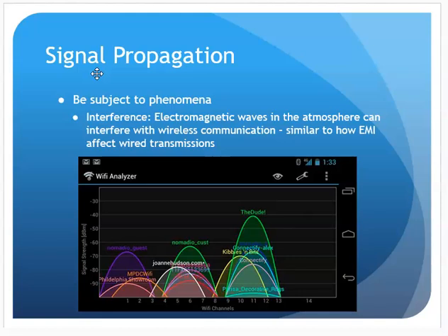There are plenty of things that are broadcasting in our wireless bands now. And I grabbed this sample offline, but this would be, if you use a Wi-Fi analyzer wherever you live, if you live in a neighborhood, you're going to end up seeing this. You're going to see a ton of SSIDs on different channels in your frequency band. These could be all of your neighbors. Well, if I'm trying to use this channel here, I have a lot of neighbors with the same channel that